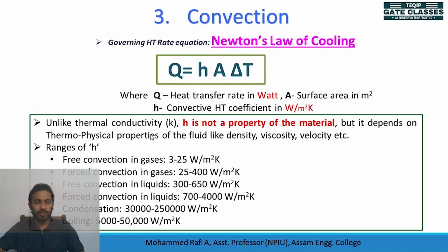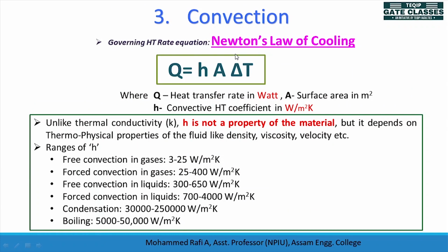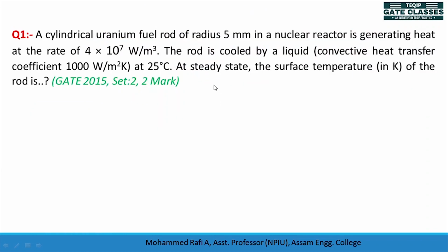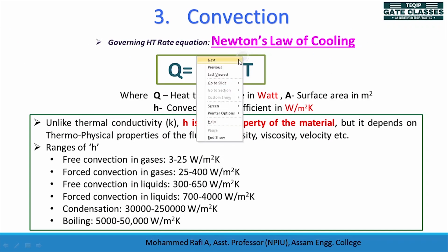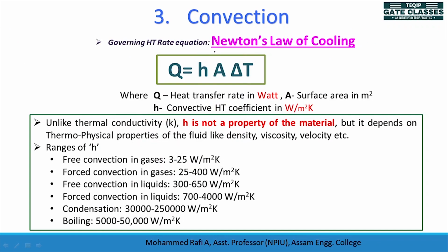In governing equations of convection, it is a contribution by the famous scientist, yes, Newton. Just like in any other field, Newton gave an enormous contribution in heat transfer also, in the form of Newton's law of cooling. So here, just like in conduction, heat transfer rate was observed to be directly proportional to the surface area and also the temperature difference T1 minus T2. This temperature difference we express either in degree Celsius or in Kelvin, and area in meter square.